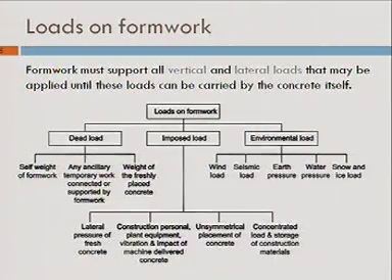Under imposed load, the major thing is the lateral pressure and the live load coming from construction personnel, plant and equipment, and then there are unsymmetrical placement of concrete, sometimes concentrated load. We will see each one of them in detail, and first we go through this dead load of formwork.